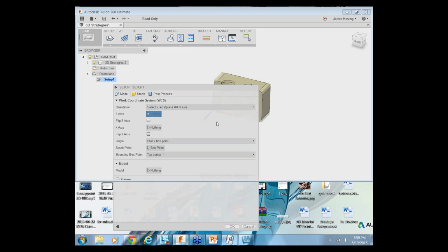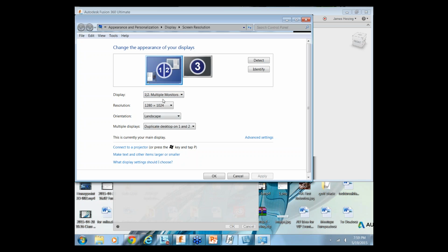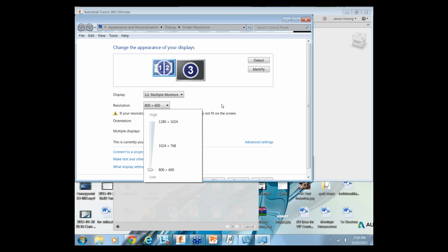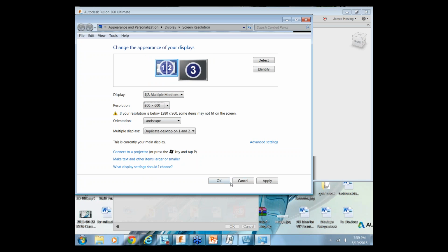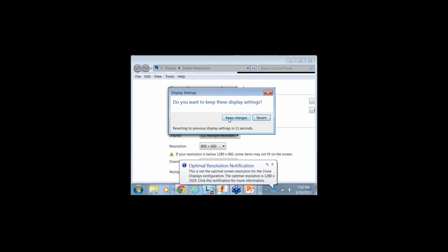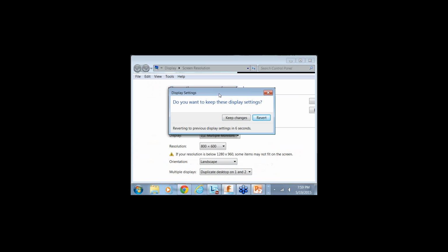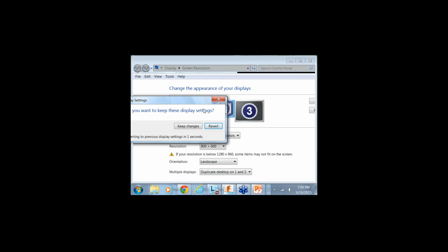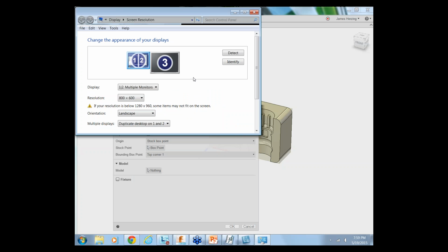Okay, but the last one, to me, was kind of 3D, but we just took it out of the vise and put it back in a different way. That's the half D? Yeah, that's the 2.5. Okay. But then with a 3D, you still have to take it out of the vise and change axes? For like undercuts and things? Yes, undercuts, anything like that, you have to reorient the part unless you have a 5 or 6 axis CNC mill, which can then rotate its head at an angle or rotate the part at an angle. Usually it's the part to allow you to get to that undercut.